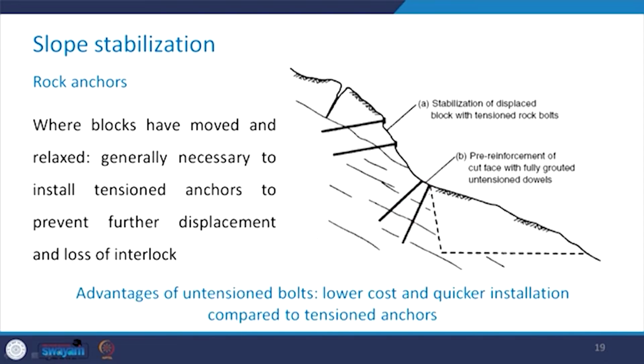When blocks have moved and relaxed, then it generally becomes necessary to install the tensioned anchors to prevent further displacement and the loss of interlock, which has been shown here in this particular portion where these tensioned rock bolts have been used. The advantages of untensioned bolts include their lower cost and quicker installation as compared to the tensioned anchors.